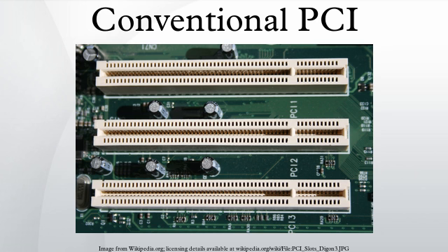This allows cards to be fitted only into slots with the voltage they support. Connector pinout. The PCI connector is defined as having 62 contacts on each side of the edge connector, but 2 or 4 of them are replaced by key notches, so a card has 60 or 58 contacts on each side. Pin 1 is closest to the backplate. B and A sides are as follows, looking down into the motherboard connector.